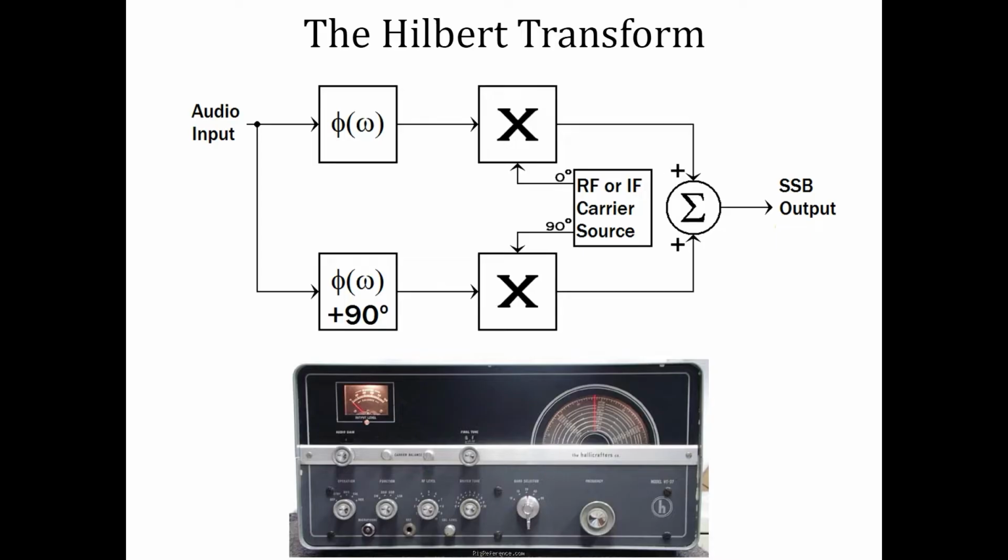But even in filter-type sideband transmitters, we still get a Hilbert transform even though we don't try to produce one directly. Think about the case where you are receiving a sideband signal with a BFO at the correct frequency. Now, if we shift the BFO phase by 90 degrees, it shifts all the demodulated audio frequencies by 90 degrees too. There's your Hilbert transform. And wherever you have a Hilbert transform, you will have lots of overshoot.